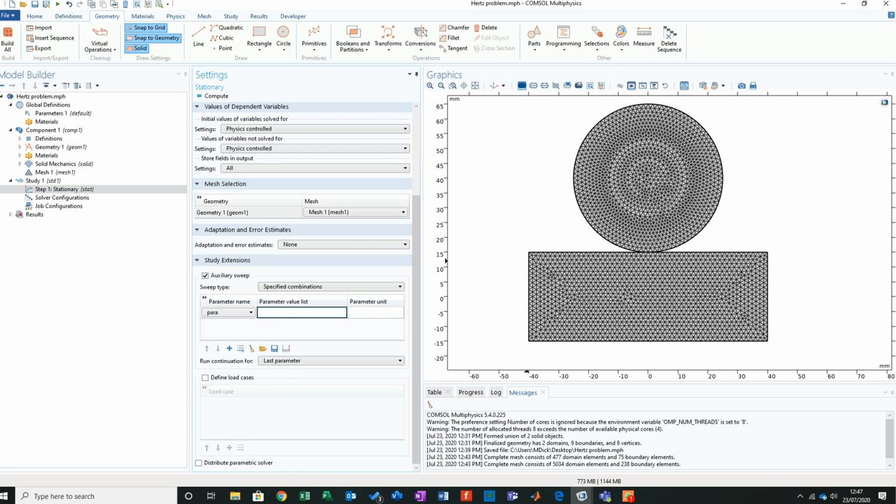Nice. So within my parameters, I want to set a range. I'm going to open that up. Where should we start from? As ever, let's start from 0. Then we're going to increment by 0.01. I have to just double check that. And then we're going to result at 0.28. You'll notice no units on there because this is totally dimensionless. What it will do is increment itself and run intermittently at 0.01 until it meets 0.28.